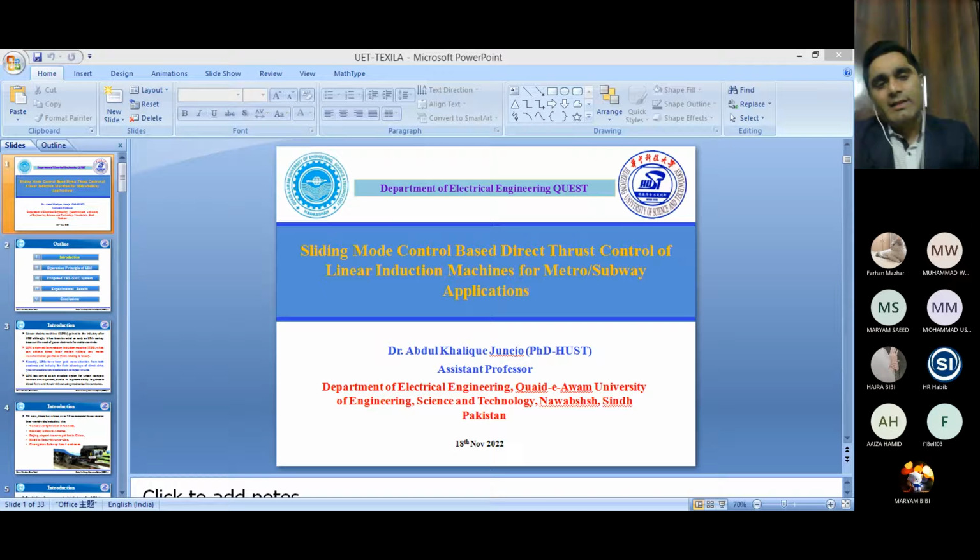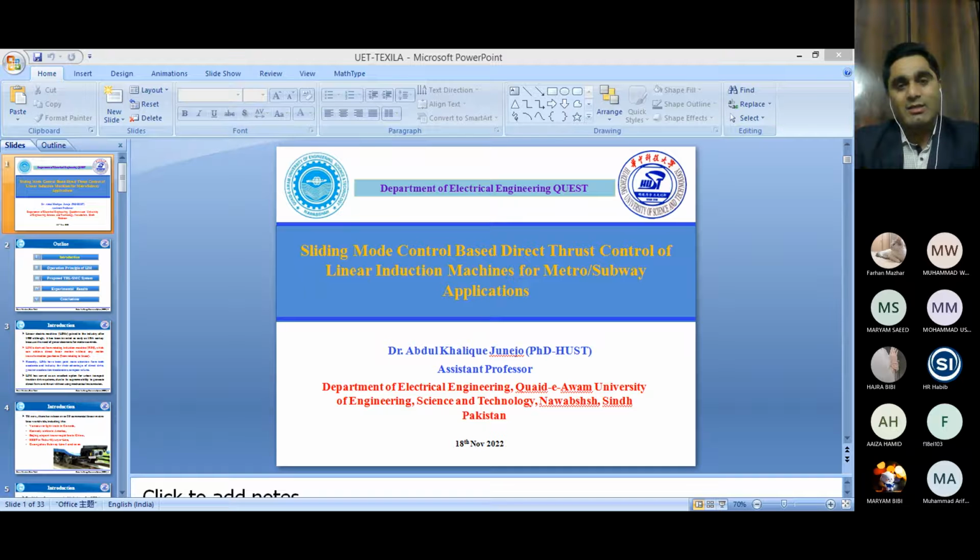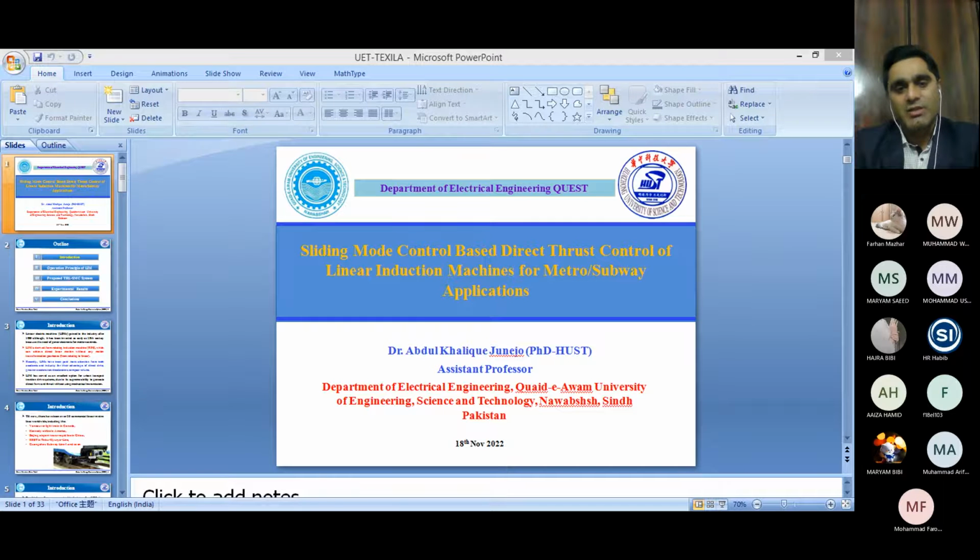Introduction: linear electric machines gained industry attention after the 1960s, although they were invented in the early 19th century, because of the need for power electronics for motion control. The LIM is derived from the rotating induction machine and achieves direct linear motion without any motion transformation gearbox. Recently, LIMs have received more attention from both academia and industry for their advantages of direct drive, greater acceleration and deceleration, and compact volume.